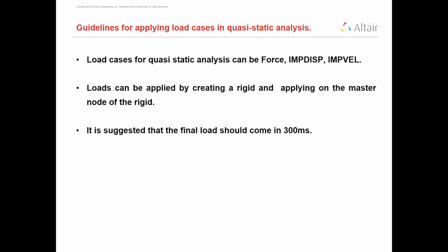These loads can be applied by creating a rigid and applying them on the master node of the rigid. It is also suggested that the final load should come in 300 milliseconds. That is, the runtime that you are specifying should be 300 milliseconds.